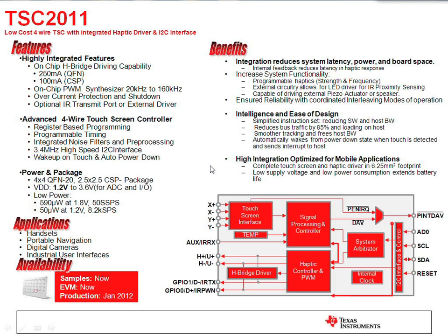So for the TSC 2011, we have the standard 4-wire interface for the touchscreen controller with an integrated haptics controller built into it. So we'll have a 250 milliamp output for QFN suitable for eccentric rotating masses, or ERMs, and linear resonant actuators, or LRAs.